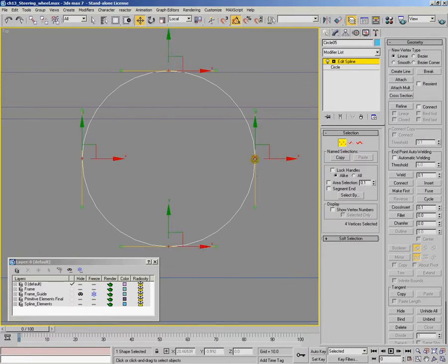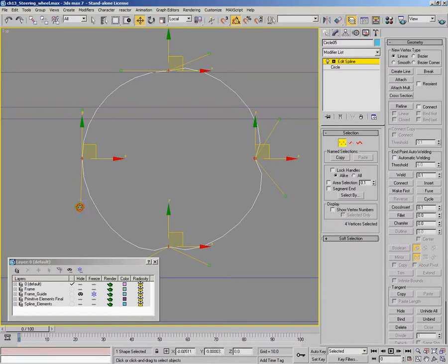What I'm going to do is I'm going to say these are now Bezier corners. I'm just going to make sure that I'm in XY mode, and then I'm going to just make some adjustments with these. Let's say like this, and like this. What I'm doing is I'm just building some grooves here. And these will give the impression of being sort of pieces of wire. It's like a 4-piece wire cable. So you've got one bundle there, one there, one there, and one there.